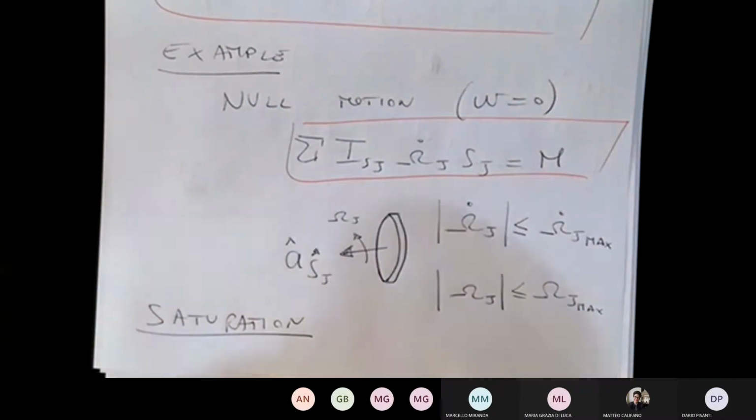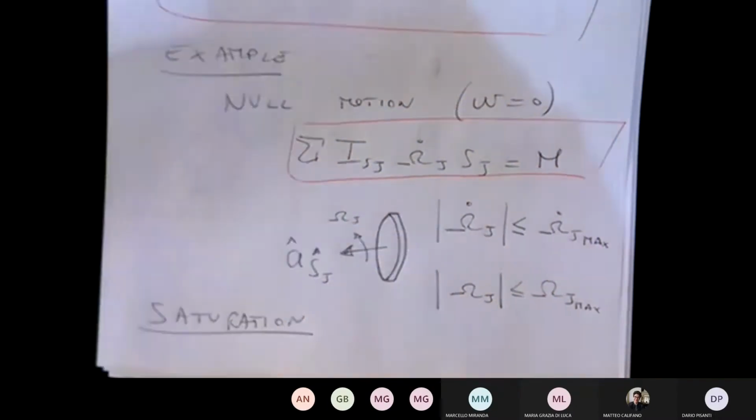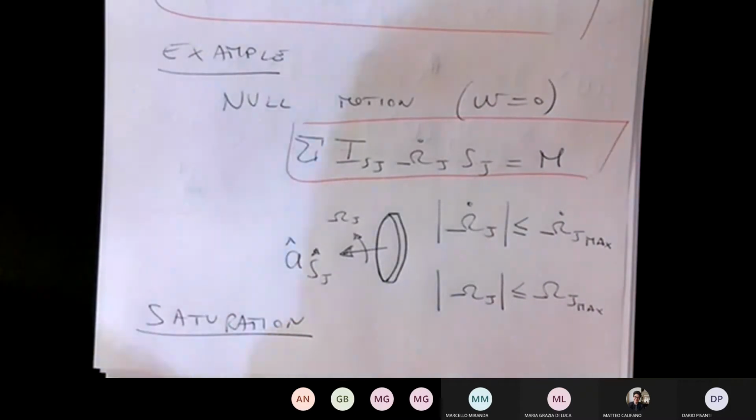So that is one problem with reaction wheels. They have, as everything, physical limitations, and if you are not careful enough in the way you're using them, if you don't keep into account in your control law and your maneuvers their state in terms of RPM, you can reach the maximum, and once you're there, you need to desaturate, and that creates a torque, and so you have to compensate for that torque, and that's a problem. Okay, so that is one case, the simplest.